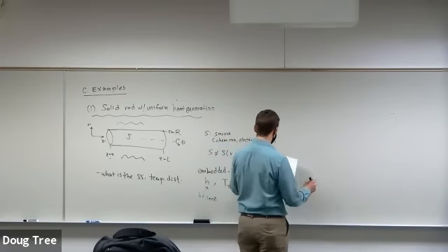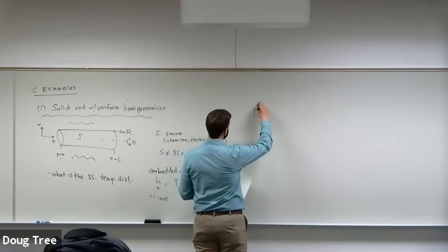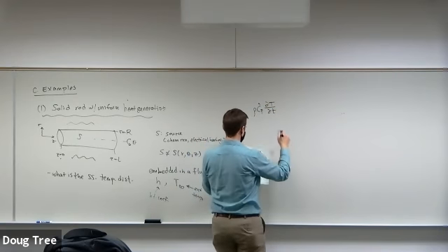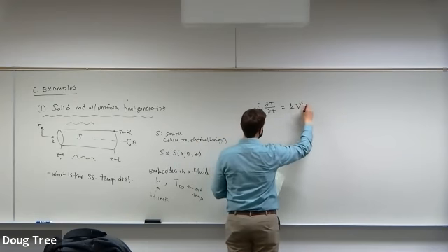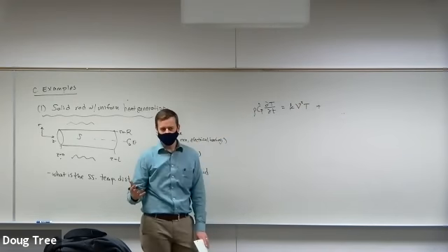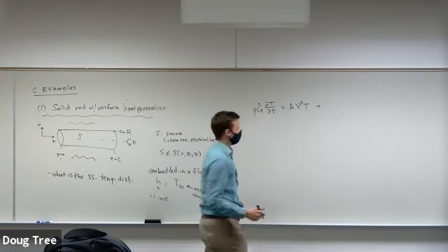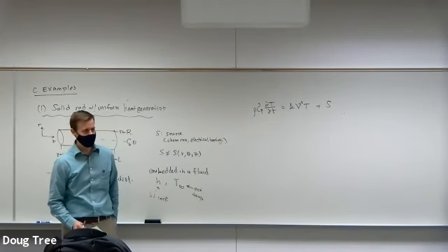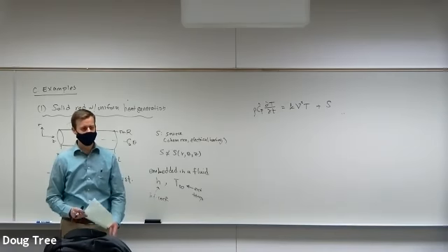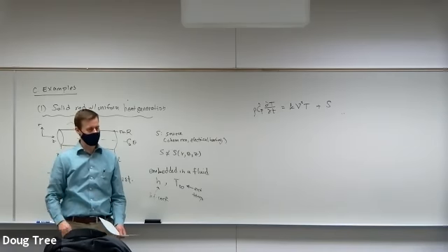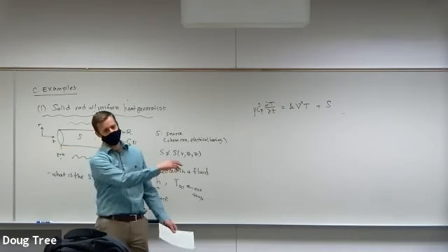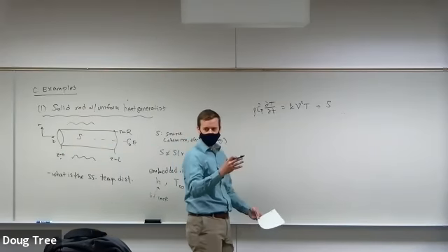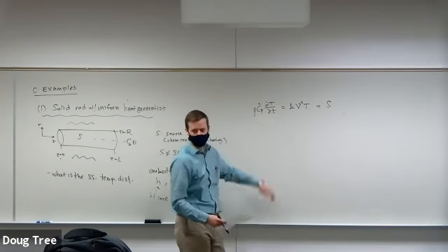We already know what it's going to be for a solid. So for a solid, we get rho C sub P dT/dt is equal to k grad squared T. Okay, but we need to add something else on because we didn't do it with a source before. So now we're going to have a source term. We add on a constant source. We could go back to our energy balance and go through the whole thing. If you remember, there's just a generation term in the energy balance. We could throw S in. We could go through the whole last two classes, and we'll just end up with the S there. But if you want to think about it from very first principles, you can do the balance and get that out.